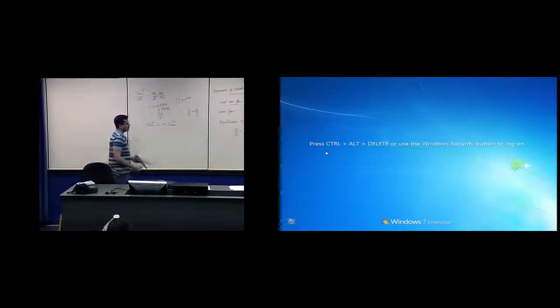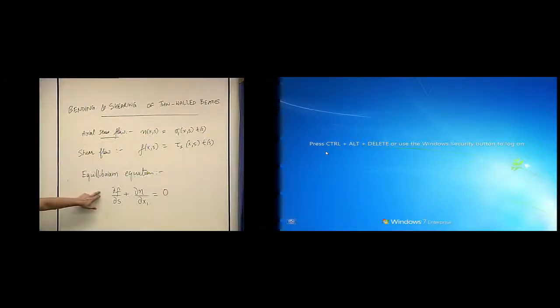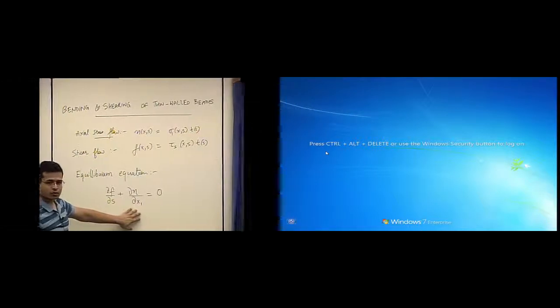So, if we have to evaluate shear flow, then we need to evaluate the axial stress flow, and if there is a given loading, for example shear forces in the beam, then we can calculate the axial stress from the formulas we did in bending of a 3D beam.